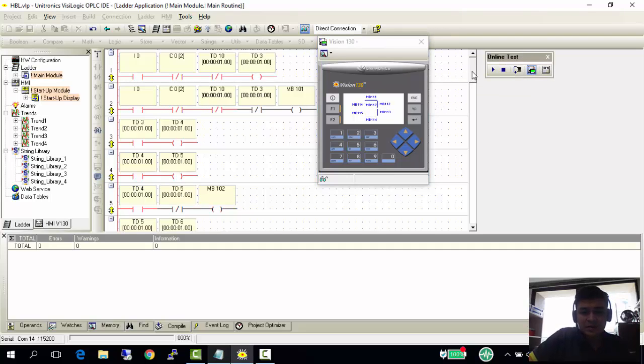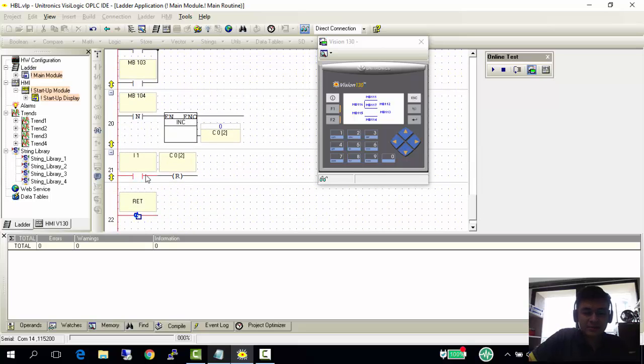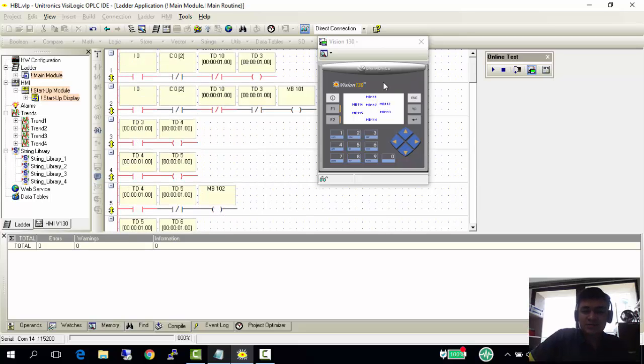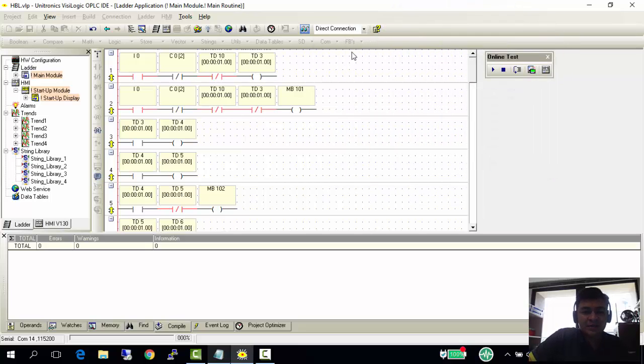You will wonder why the counter is non-stop moving. Why? My I1 is now switched on. So take note, I have to clear away the I1. That means it should only count up to 2 here, and then it will stop. Let's wait for the count of 2. So this is using a counter example, which we did in our home-based learning.